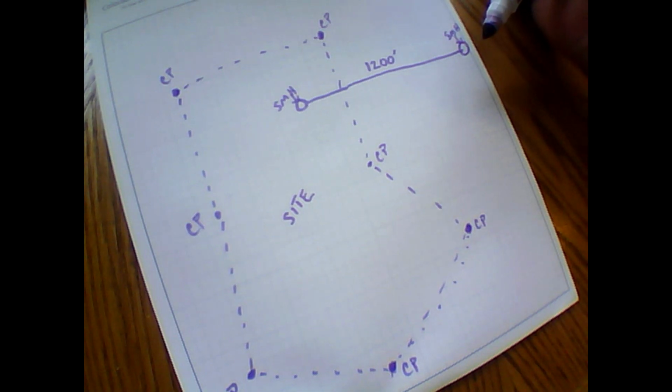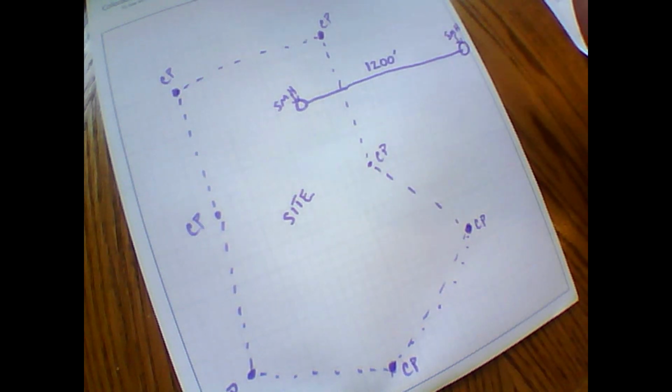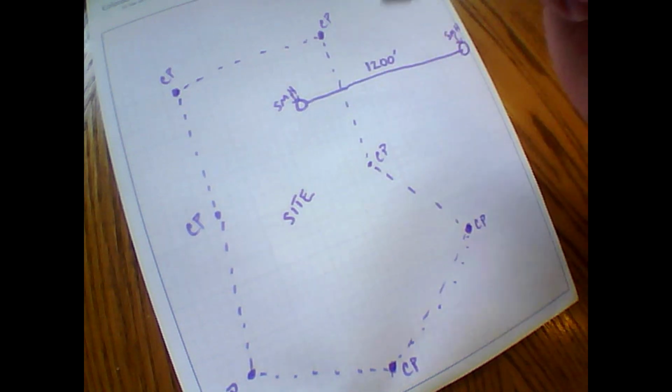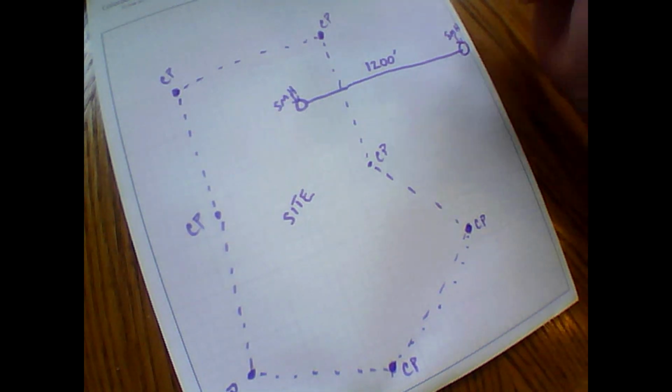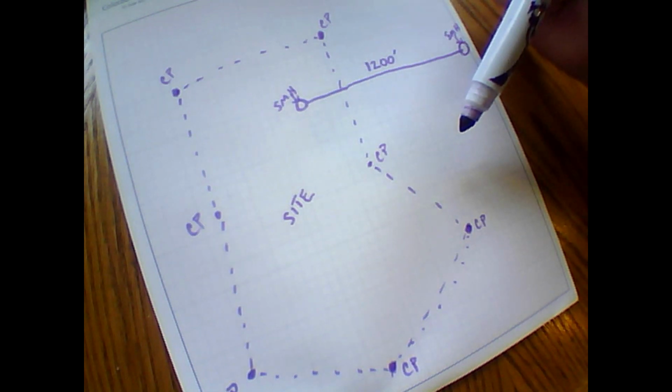That introduces too much distortion for me. I think for a manhole, a sanitary manhole, you'll get away with it. I don't think anyone's going to have an issue. You're not going to end up 40 feet from where you're supposed to be or anything like that. I prefer not to do it, being limited to the site and then going 1,200 feet away. I prefer this. I basically tie every single point. Those are my check shots.